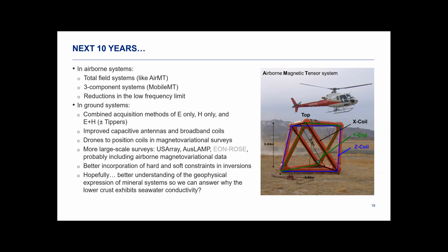And I would say especially we need to learn how to put the physical properties in the inversions. Borehole resistivity surveys are great, but if you think about it, you have a mesh or a voxel model that has 500,000 cells in it, and you have a few holes that each touch 20 cells. How important is that? How can you make those data meaningful? And what do the borehole resistivity data actually mean?